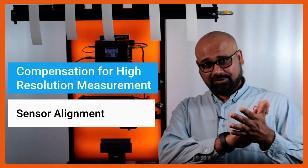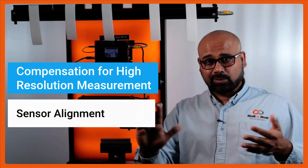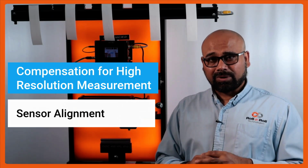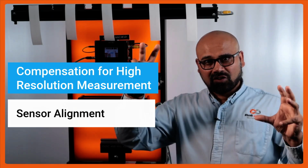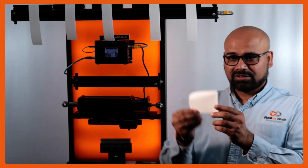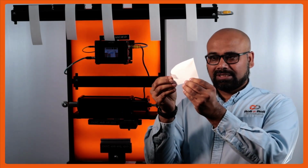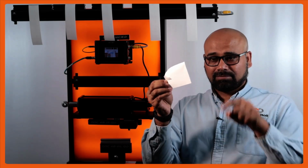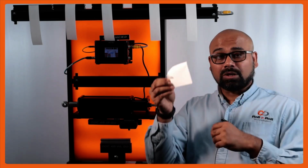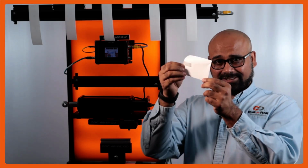Obviously, we want the sensor face to be parallel to the surface of the web, and we want the sensor to be at a certain distance from the web, but it can be installed at an angle, and even small angles make a big difference in the measurement. So the example would be, if I have a sample that is straight, but if I put it at an angle, then I'm looking at essentially, it's basically a cosine kind of thing. So you are adding more to the width than that. So there is an issue with how the web is presenting.